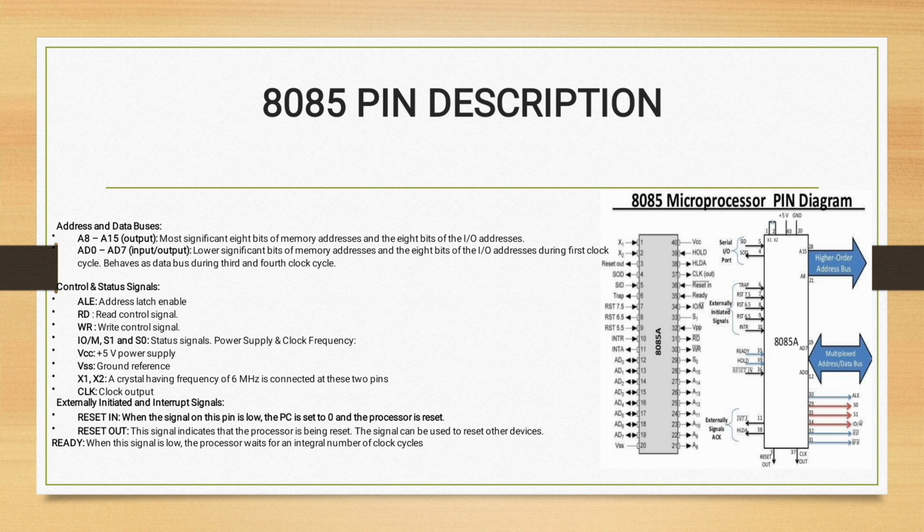And reset in and reset out, these pins are externally initiated by some device. Reset out is an output pin. It indicates the CPU is in the reset condition, and reset in is the input pin. It resets the PC, the program counter, to 0.